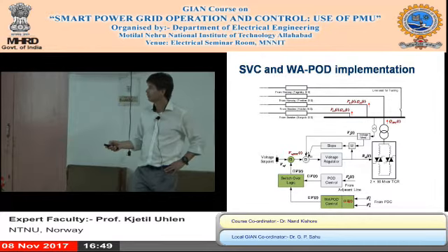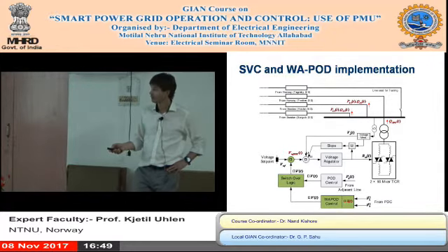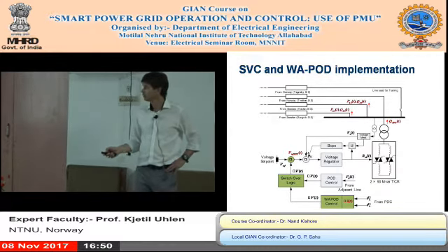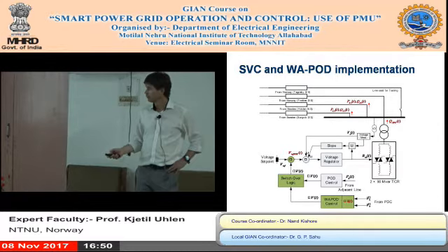It is equipped with an auxiliary control input that is usually the local POD, which measures the power on the line. But what we developed was the wide area power oscillation damper that took the angle difference from the two remote sites through the controller and added that as the control signal.